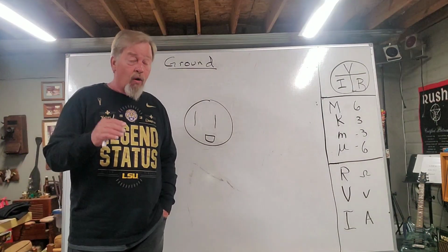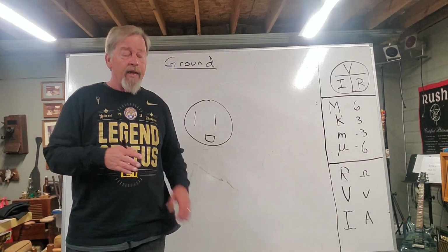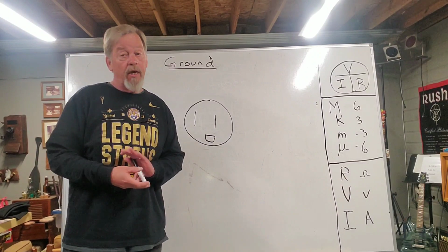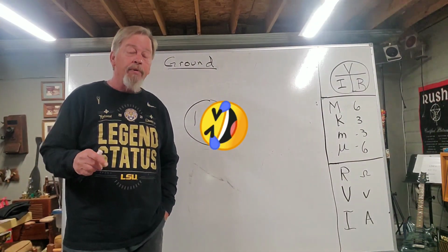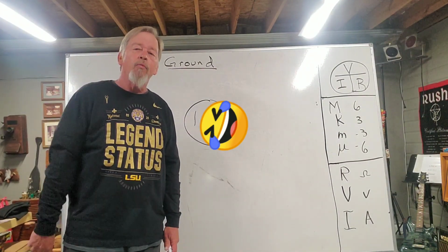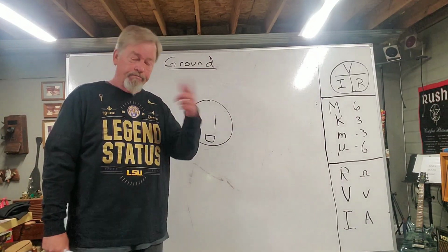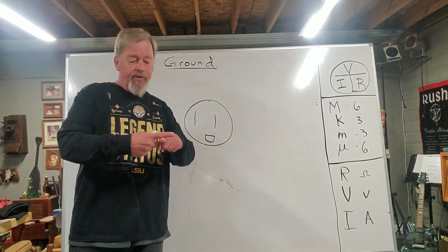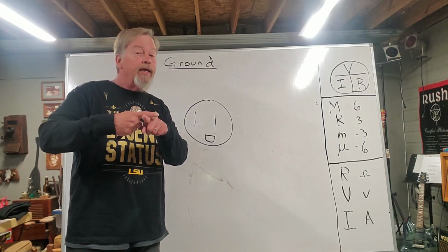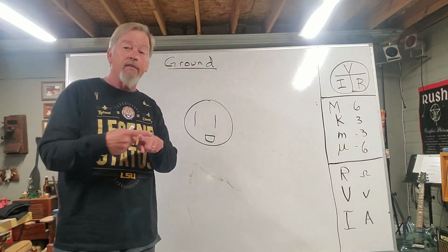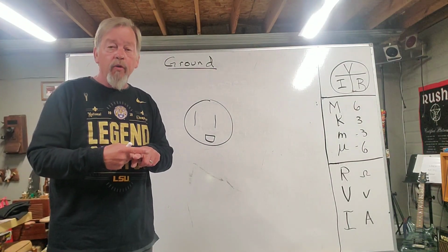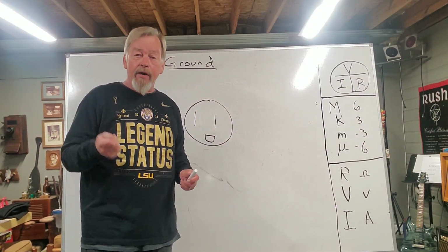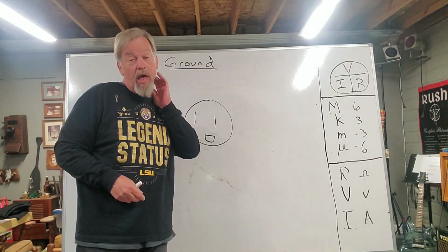And it went round and round because my grandmother's refrigerator, on a bad day, you could walk up and grab the handle on the refrigerator and just get shocked. I'm telling you that we didn't like it. My grandmother used to keep an oven mitt by the refrigerator so she could open the door. And as I got to realize later on in life, what had happened was the power cord, because of the vibration of the compressor and the motor, was rubbing up against the metal frame. And it eventually wore down till it had bare wire up against the frame of that refrigerator. So that put 120 volts on the metal outside of that refrigerator. So anytime you walked up to it, it was just like taking a butter knife and sticking it into a receptacle. Lord of mercy, it would light you up.